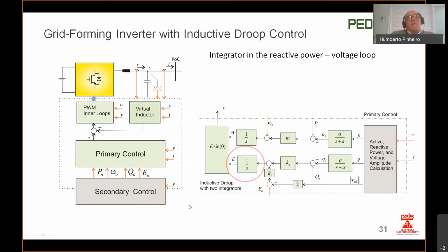So here what we have noticed is that we had this steady state error. In order to compensate for that, you can introduce an additional integrator on the voltage loop. So we have now 2 additional parameters, actually 1 additional parameter.